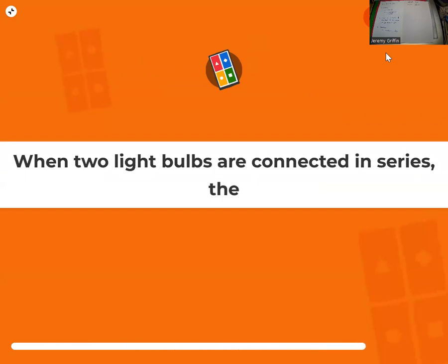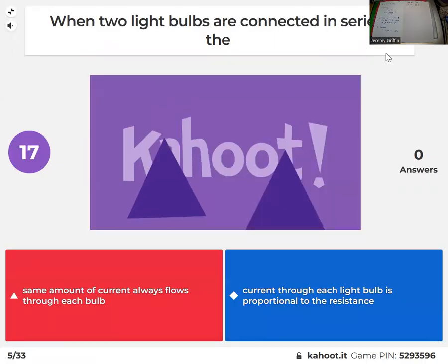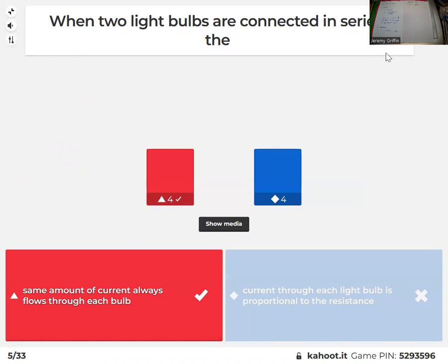When two bulbs are connected in series, what's true? All right, yes, it's the same current that flows through each bulb, regardless of what the resistances are. Bring up Kirchhoff's rules again. So we're talking about this one right here, series. You guys remember this right here? The current's the same everywhere. Okay. Now, they could be like 1 ohm here and 99 ohms here. It doesn't matter, it's the same current.